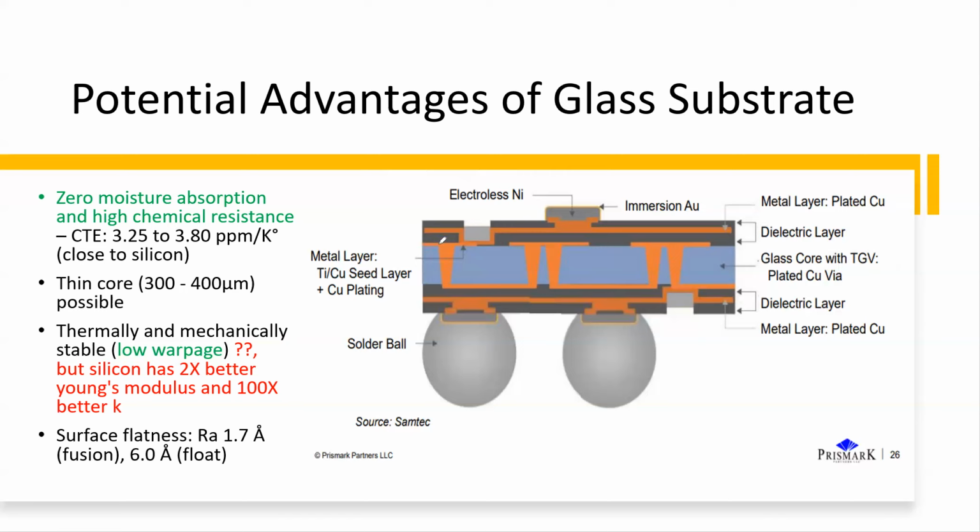Then the next question is, how am I going to drill these holes? Is it easy? Well, SiO2 is not a big problem, right? But this hole is large. It's not like IOD or the back-end layers, where you're at nanometer scale. So you use dry etch. And this is 100 microns, which is still a thin one. Imagine a thick one, 1,000 microns, and you want to drill holes with dry etch. You're crazy, right? I don't think it's going to work.